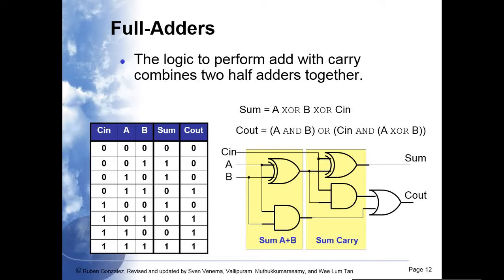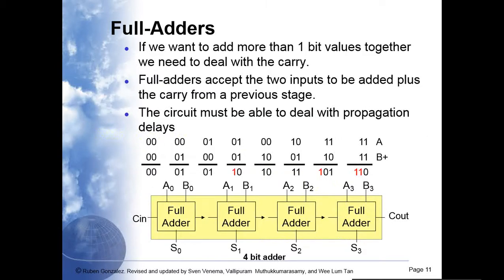How many bits does a full adder work on? 2 bits. It adds 1 bit to another bit. Is that enough? Not even close, right? We want this slide. You'll see how we've got a bunch of full adders glued together. If we have 8 of them glued together like this, and they talk to each other so the carry goes between them, we have an 8-bit addition unit. What kind of machine are you working with at the moment? Is it an 8-bit machine? 64-bit? So probably you have a much bigger addition unit than the ones we're talking about. But the principle remains the same, right?